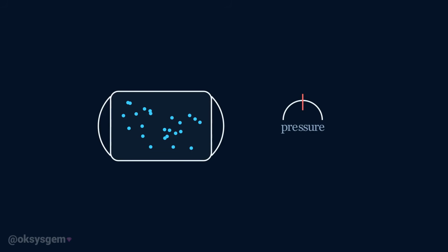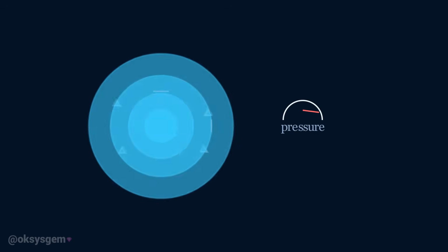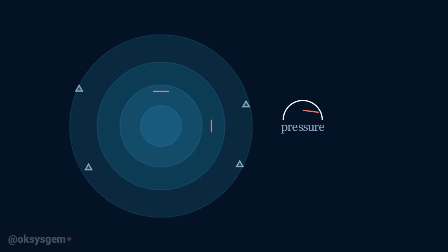Level 1, Mechanical Explosions. The simplest kind of explosion does not require any burning at all. A mechanical explosion happens when pressure builds up inside a container until the material holding it can no longer resist the force. When the container suddenly breaks, the compressed gas or liquid inside expands rapidly, pushing the surrounding air outward and throwing fragments of the container away.